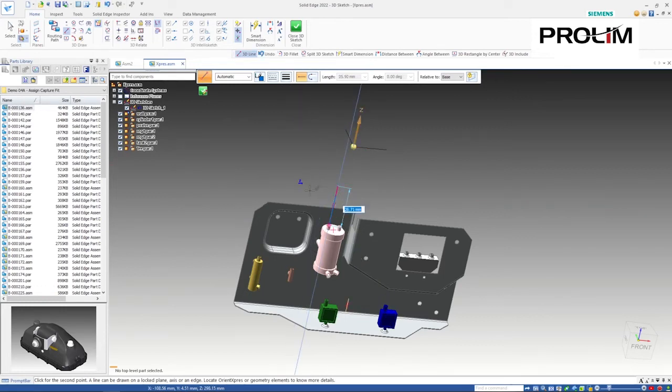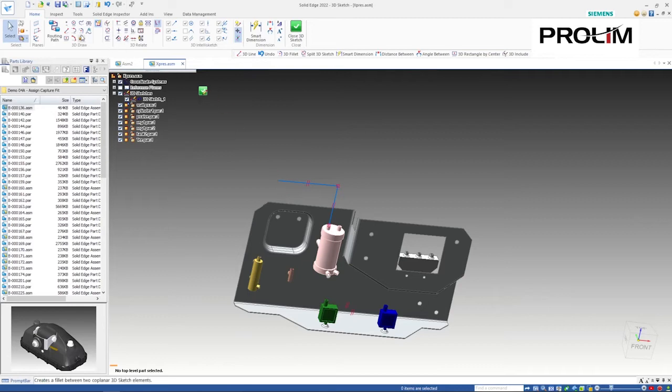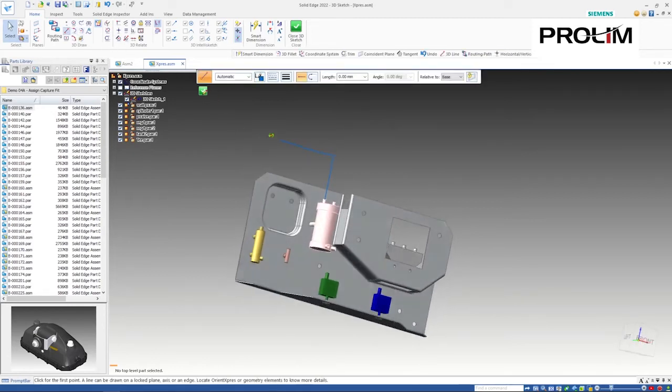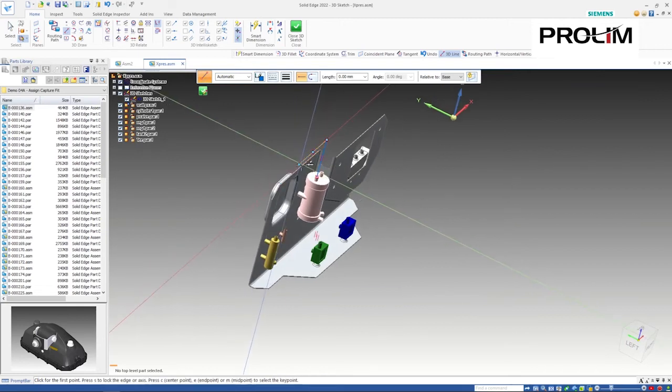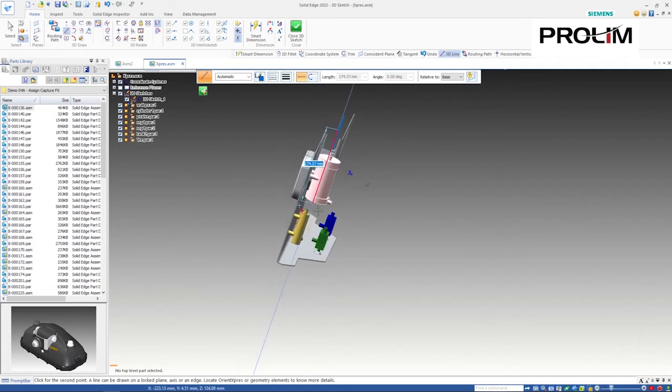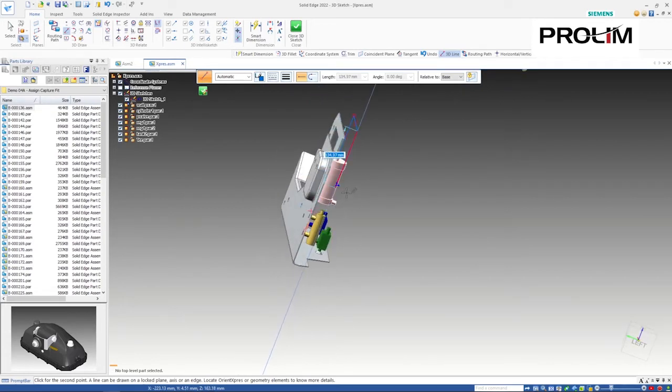Now this time, I'm going to lock into the x-axis. And when I'm locking into the x-axis, I want to use this as my reference point. So let's select that. So it gets extended over that length. And now again, I'll just create a new line here and use the end point of my second line as start point of my third line as a reference point, and then lock into the z-axis again. I'll just extend it to a random length. Say, for example, in this case, I'll just extend it up to here.